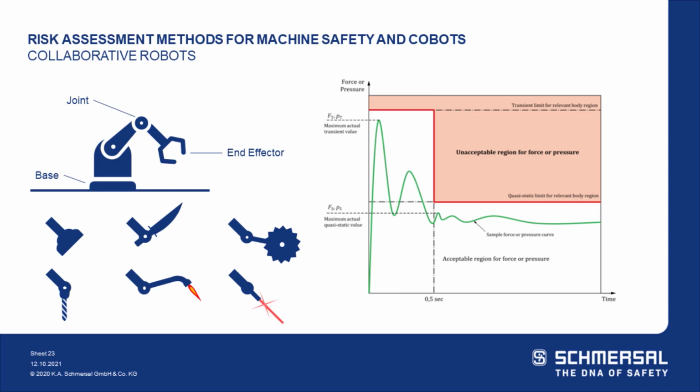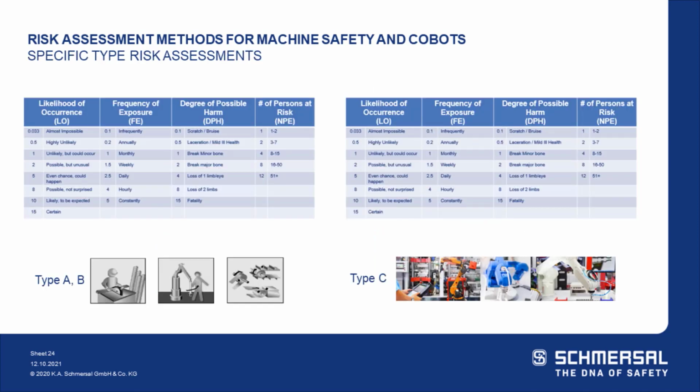And that requires the measurement of force between the operator and a part of the robot or fixed structure that is clamped. So, are we doing this as part of when we enter a collaborative robot? Are we measuring the force? There's a measurement tool you use to determine the force. So it does stop, but we've got to measure to see if the force is too much, right? And that's part of the standard. Do we know about this? Are we doing that? Is it part of our assessments?